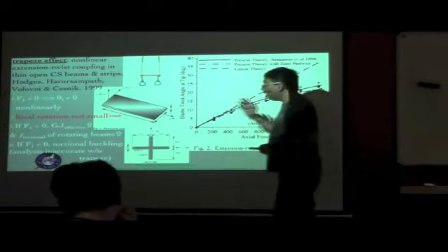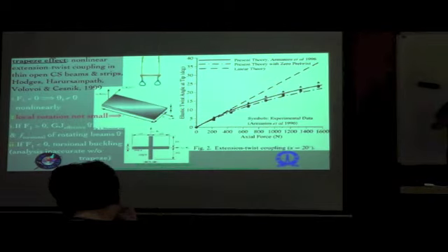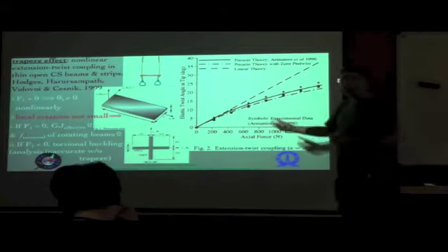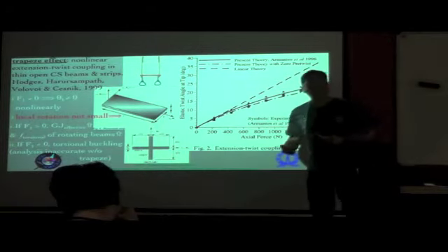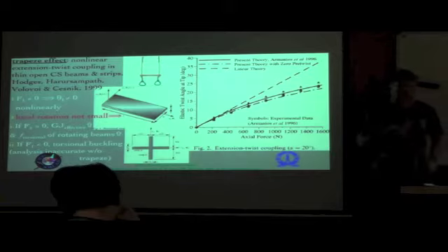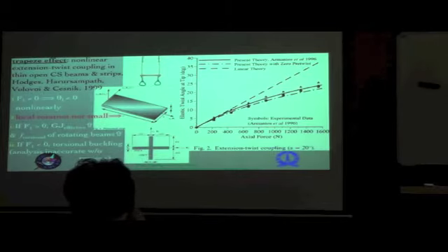If you want to determine the torsional buckling and the post-buckling behavior, in terms of how the geometry changes as you continue to increase, let's say, the axial load and or other loads which might be combined with the axial load, then unless you have a nonlinear theory which takes care of this, you will not be able to predict all of that accurately. In fact, you will be way off from what is observed in experiments. So this is as far as the physical description of the trapeze effect is concerned.